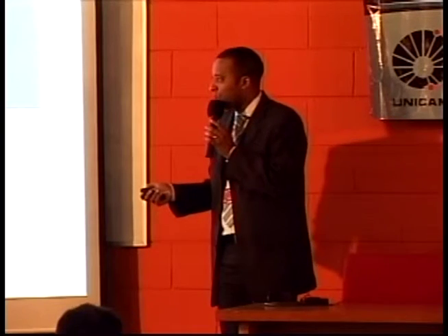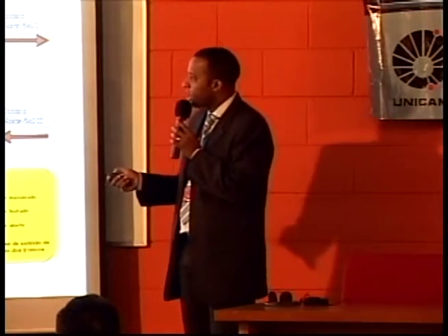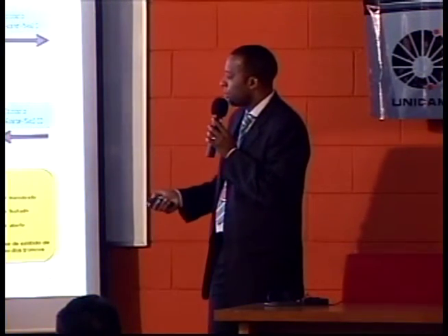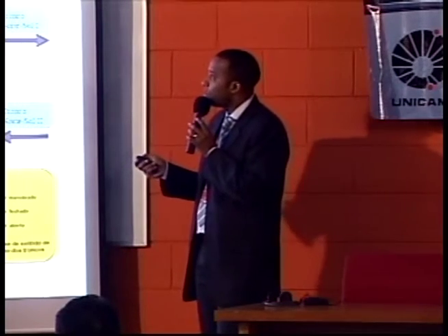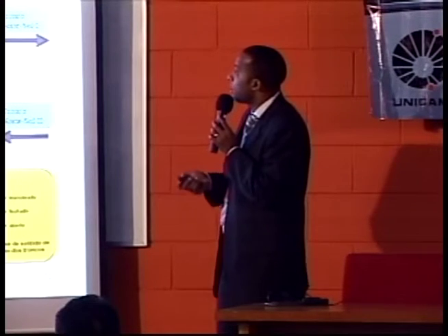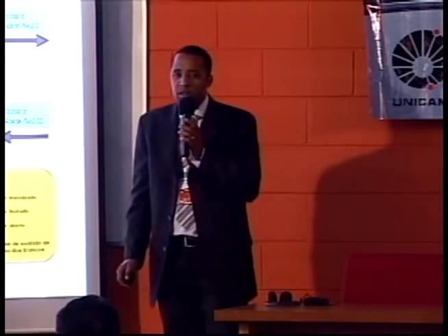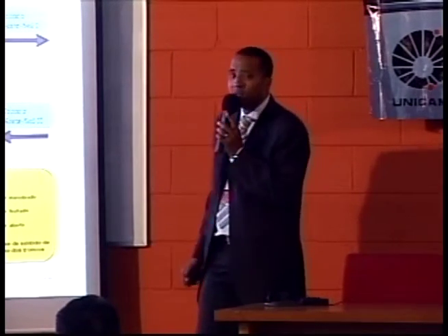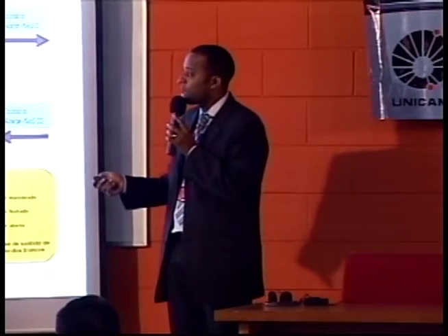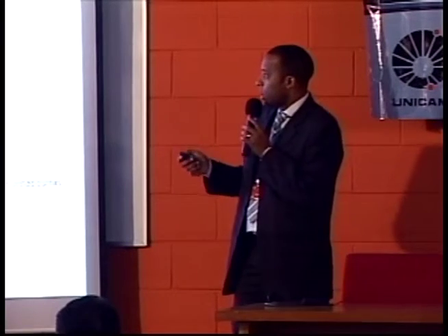Here I present the results for opening of the link with remote faults. What we did was a scanning of all the faults throughout the link, varying the application of the fault in 10% segments of the total length of the line, with the purpose of verifying all the critical or severe conditions regarding single-phase ground faults, three-phase ground faults, and three-phase isolated faults, and critical conditions for the opening of the circuit breaker.